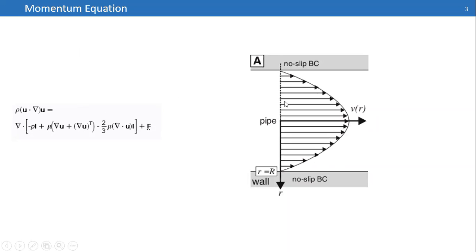At the outlet, we can just define the pressure of your system at the outlet of your reactor, since most of the time your fluid is going to be released into the environment or downstream units. It depends. You can define the pressure for downstream units here. For example, if it is released into the environment, you can define the pressure equal to 0 at the outlet.